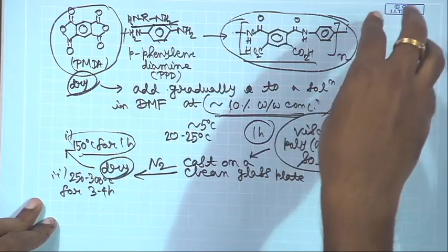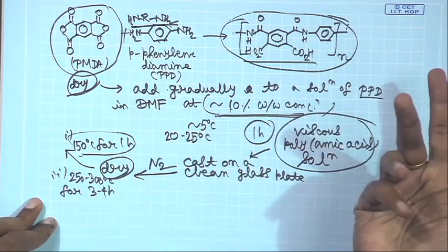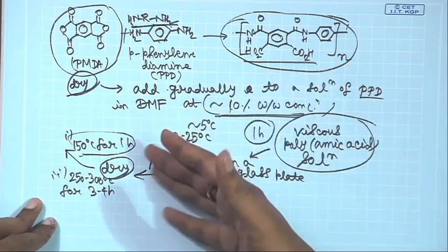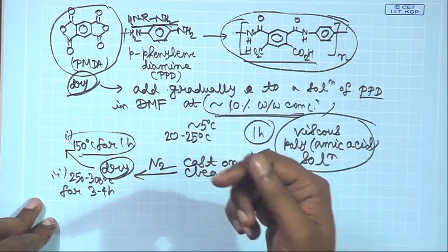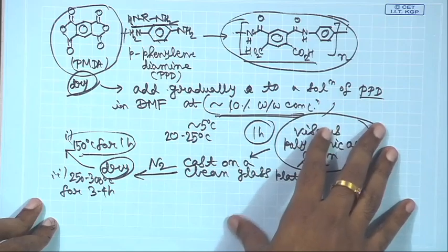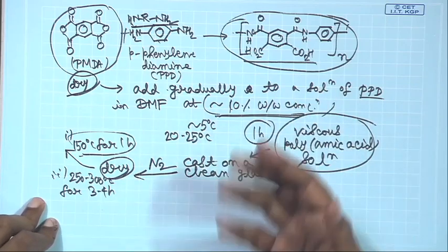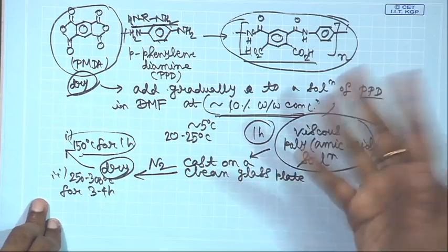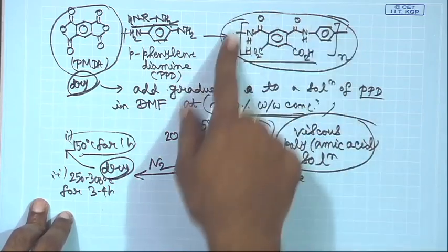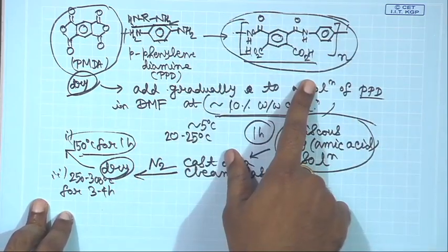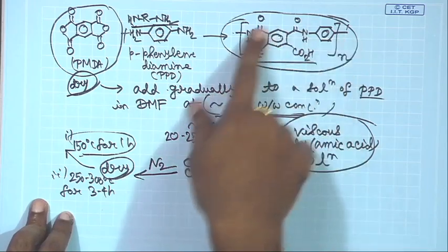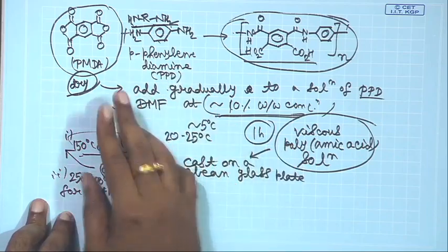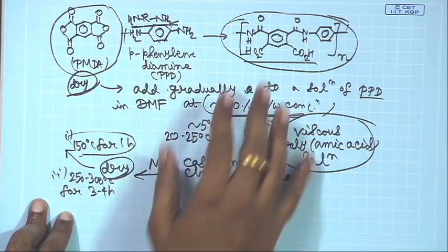Instead, if you had produced polyimide directly and tried to process it, it is difficult, because first of all you will not reach high molecular weight, because before high molecular weight it starts to precipitate out because of solubility problems in the solvent. Secondly, even if you could get high molecular weight, it is now insoluble and you cannot melt this material either. So, you cannot process it. That is why you start with polyamic acid, which is still soluble and can still be melted, and then you take it into the desired shape, remove your solvent, heat it up, cyclize, and you get your final product in the processed condition.